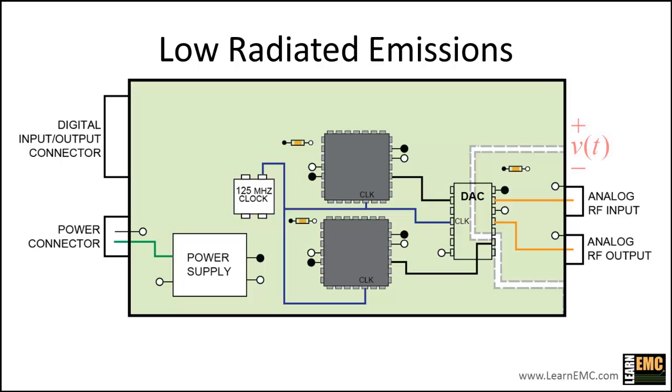We'll typically see a time-varying voltage on one of these ground planes relative to the other plane. This is not what we want, since this voltage can drive the cables attached to one ground plane relative to the cables attached to the other ground plane. By putting that gap in there, we're essentially enabling a noise voltage that drives the cables attached to the board.